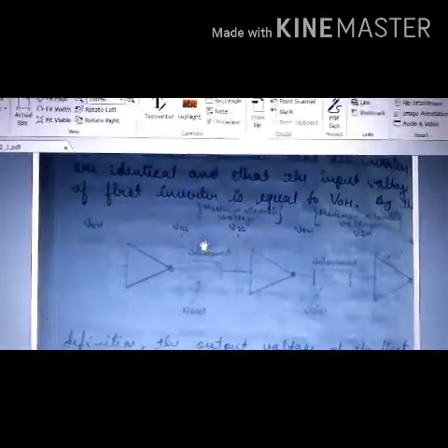In layman's language, we have applied 1 here, so the output should be 0. Now this zero output is going to the second inverter. If the voltage level, due to this noise, is greater than VIL, then this output cannot be considered as logic 0 and it will not be correctly understood, and we will not get VOH here. Therefore, whatever the output is here, the impact of noise should not raise it higher than VIL. Then only can we get a satisfactory VOH here.